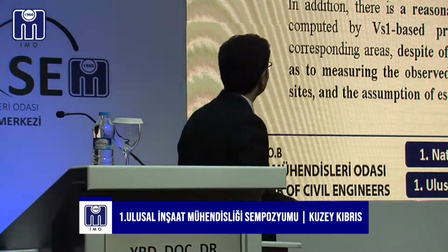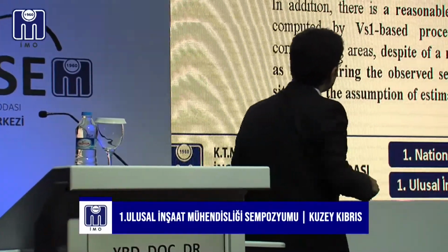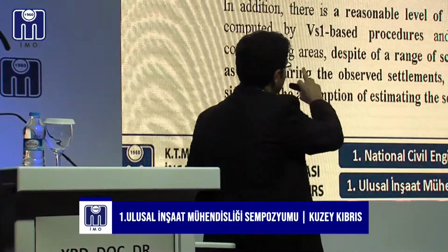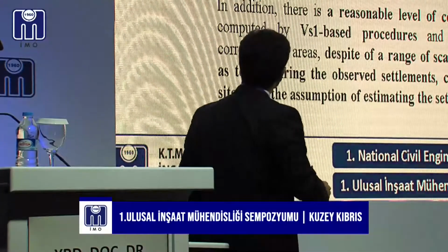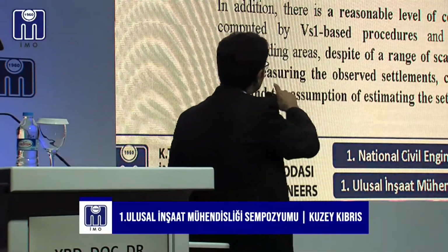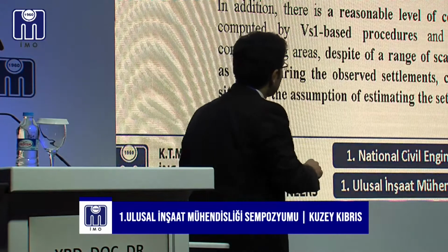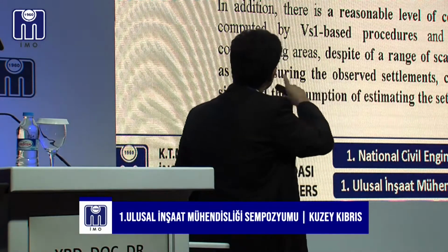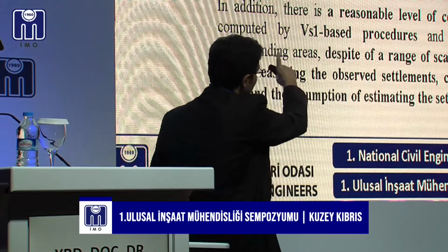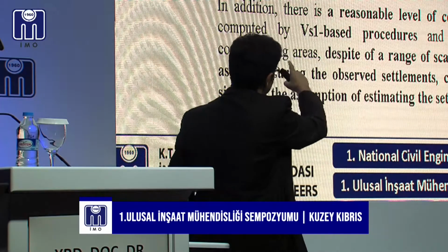The comparison between the VS-based procedure and the SPT N-based procedure used for computing liquefaction-induced settlement indicates a reasonable level of coincidence. But we have a problem with shear wave velocity.